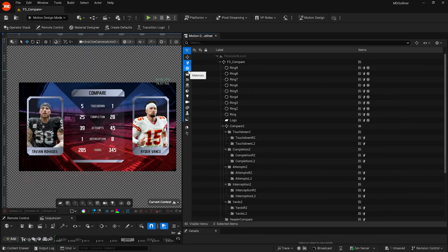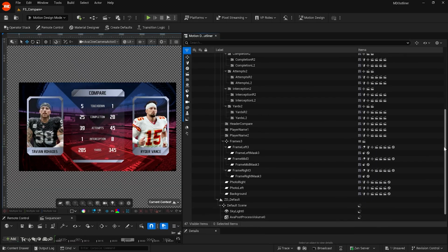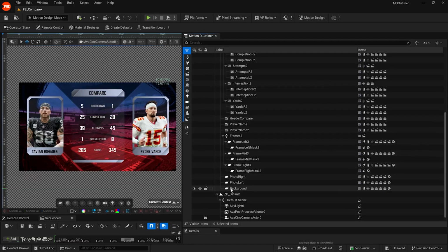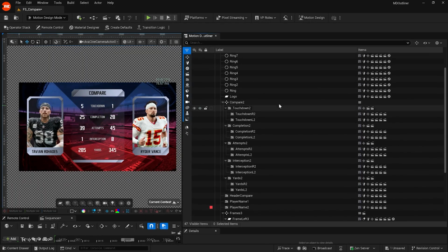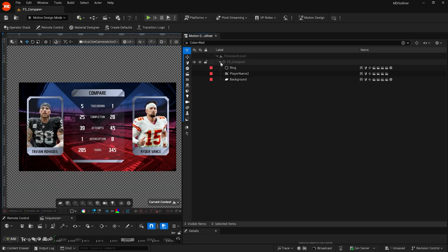If needed, you can use more than one filter at the same time. To select them all at once, use Select All. To deselect all, you can use the deselect icon. The color option is a very good tool for custom filtering. So, for example, you want to create a filter that is independent of type, item, or name. Assign the same colors to the actors you want to group for filtering. Then if you write this selected color in the search bar, you will get a list filtered by that color.